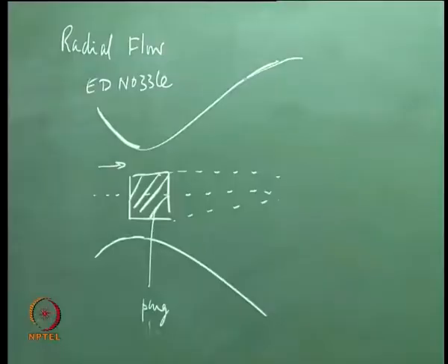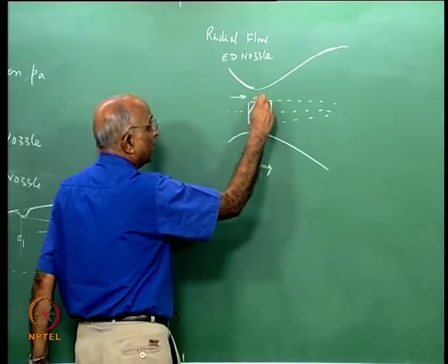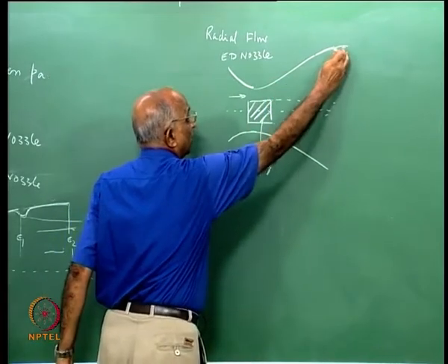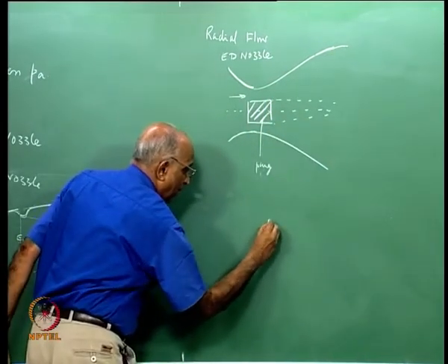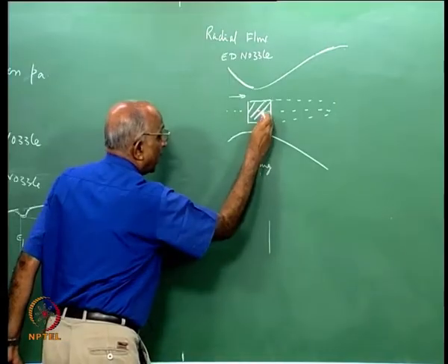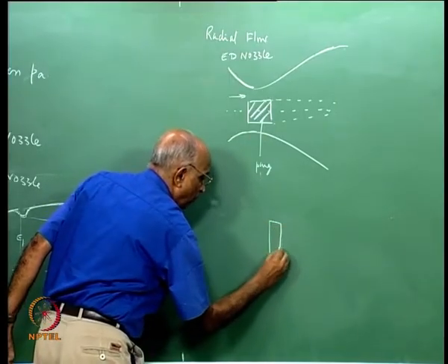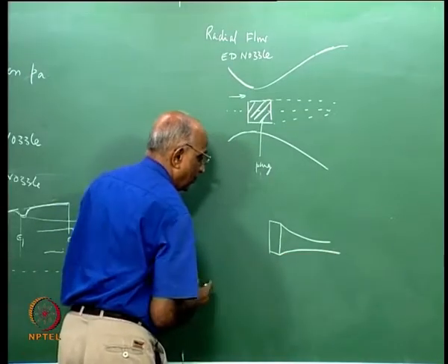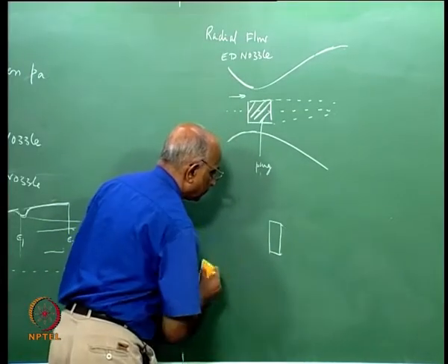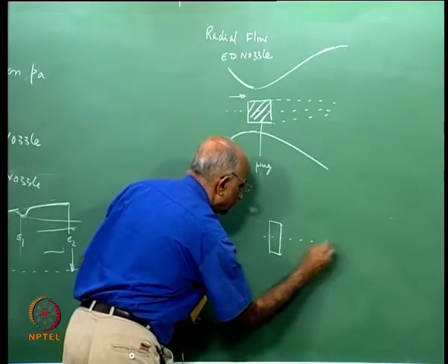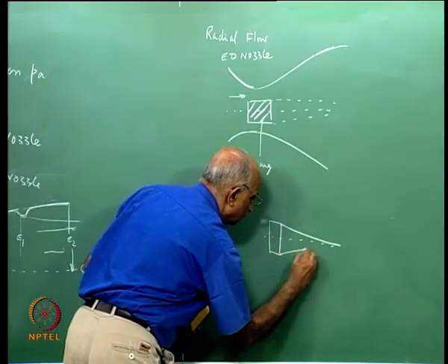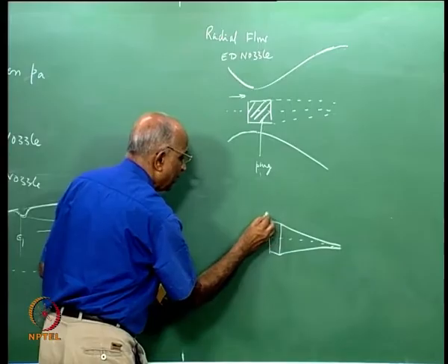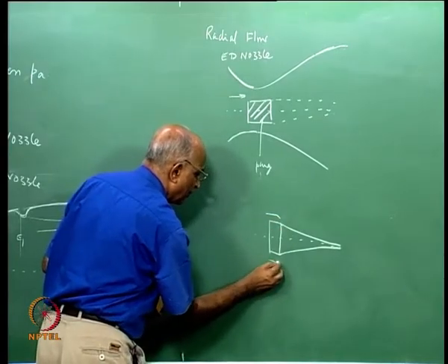As an extension of this, we could also have a nozzle, instead of having a plug here and allowing the outer thing to flow across a nozzle, I can have this plug in the form of, let us say, a contour over here, a central contour like this, and what I do is I bring the flow over here from the chamber.